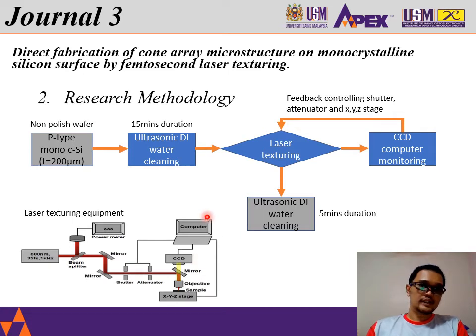Let's have a look at the research methodology for this journal. The first step is preparing the material, which is P-type monocrystalline silicon wafers, 200 micrometer thickness, non-polished. Then it moves to ultrasonic DI water cleaning for 15 minutes. Proceed to the laser texturing process.